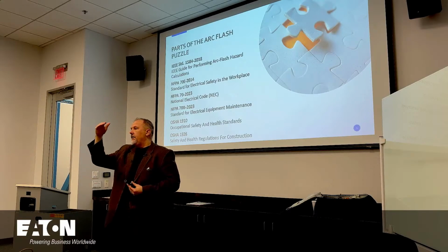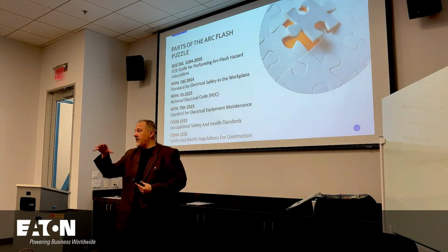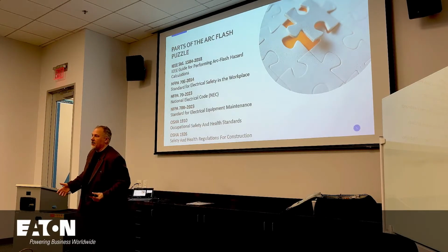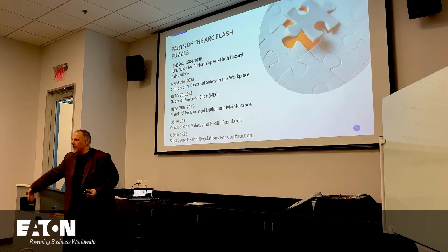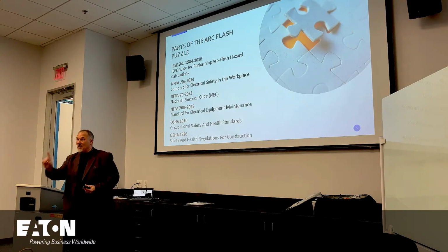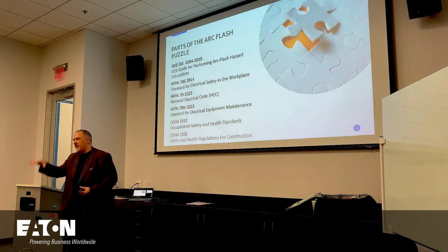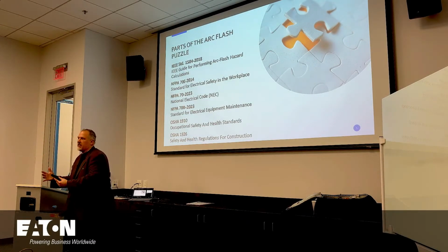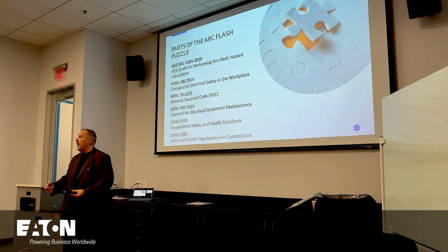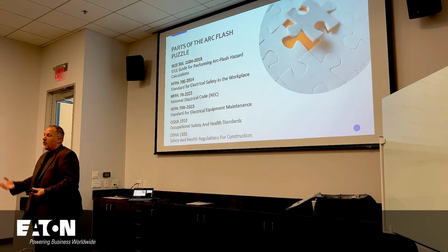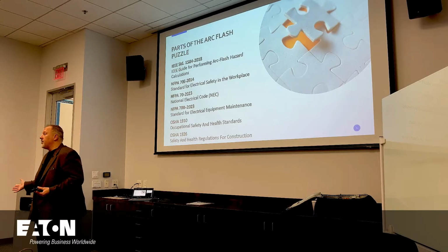So when Dr. Lee did the testing down in St. Louis, he created what we call arcs in a box, basically a big square box where we have our electrodes, and we initiate the fault, not a piece of equipment. He did test after test after test, then changed the size of the enclosure, test after test, and then changed the configuration of the electrodes. All we do is put sensors out in front to measure the heat. We don't have pressure indicators and all that to measure how much force or how much shrapnel.